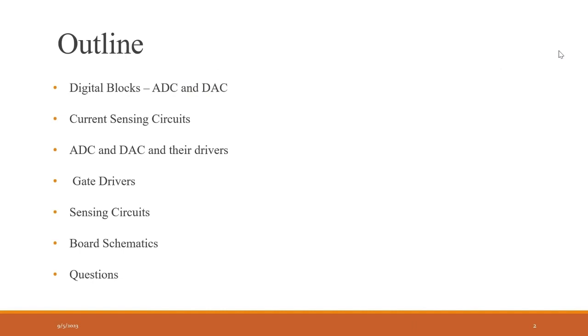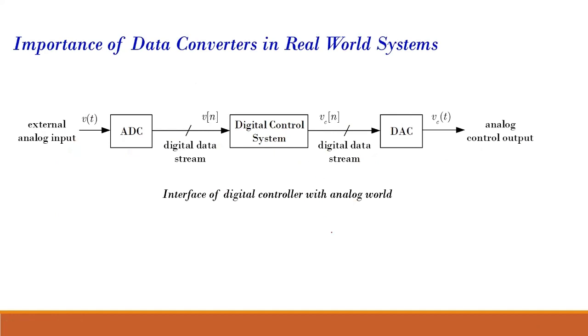In the MATLAB simulation we are not using any specific block for DAC. Let me just show you. Can you see this? In MATLAB, what we're doing is, we have an ADC sampling. Then we have the controller GC of Z, and that generates, suppose, your I reference of N. And then directly we are passing it on to the comparator in MATLAB.